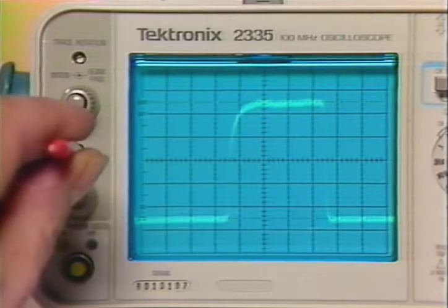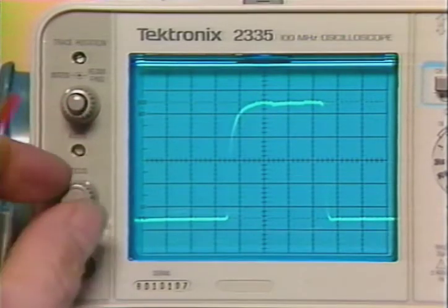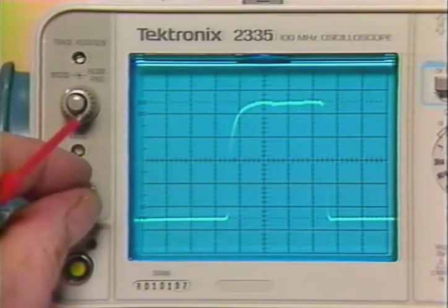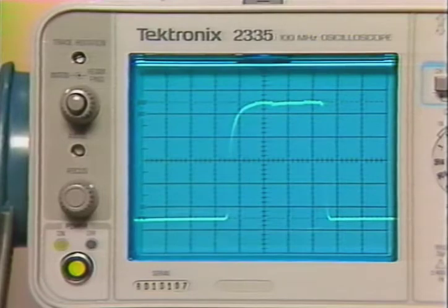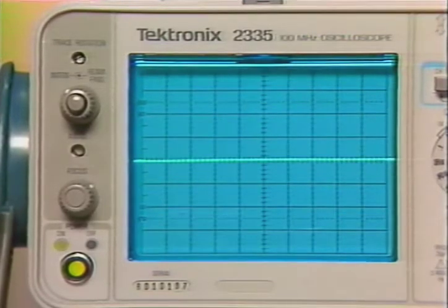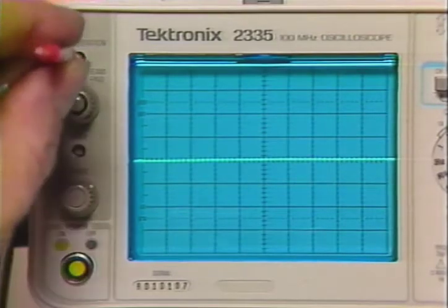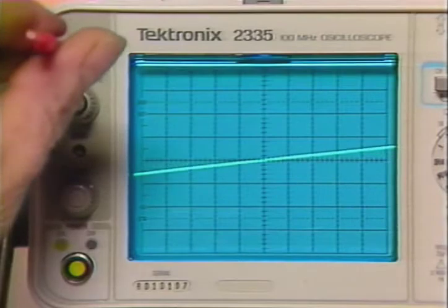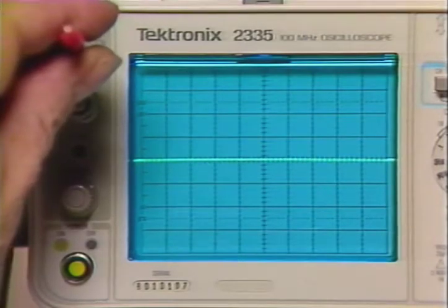Astigmatism control is a screwdriver control used in conjunction with the focus control to obtain a well-defined display over the entire graticule area, and it does not require readjustment during normal operation of the instrument. The screwdriver slot trace rotation adjustment aligns the horizontal deflection of the trace with the fixed graticule. To avoid accidental misalignments when the scope is in use, the control is recessed.